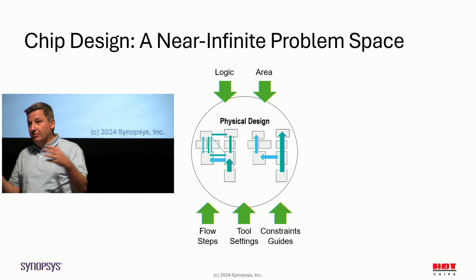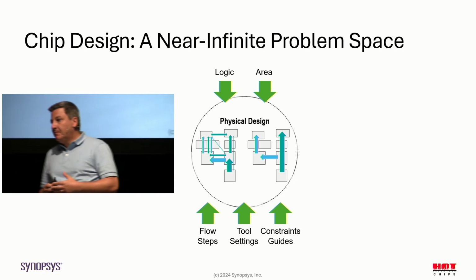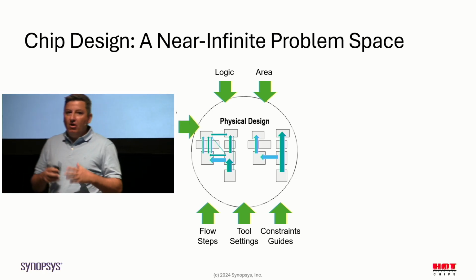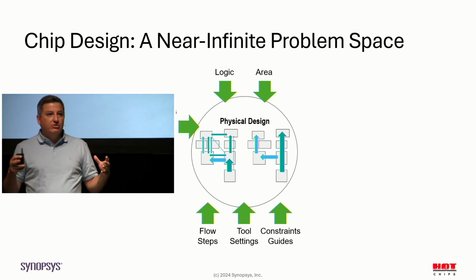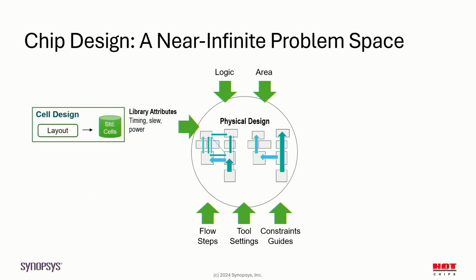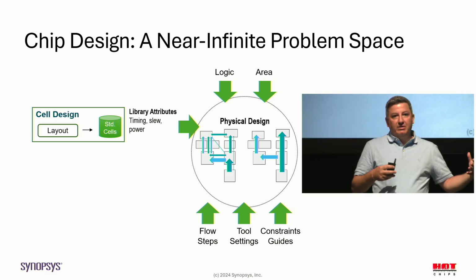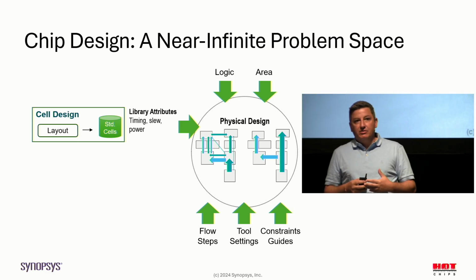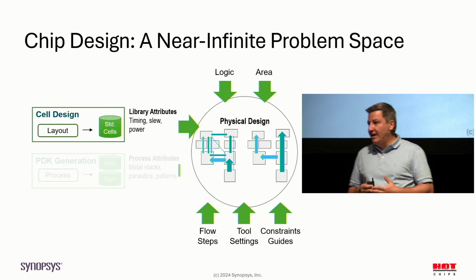All this goes into the design flow and the tooling. We also have large parameters, for example the architecture of the cells that we're using. Our teams work for a long time to optimize standard cell libraries, characterize them, and push them into design flows as options. This is an expression of optionality.